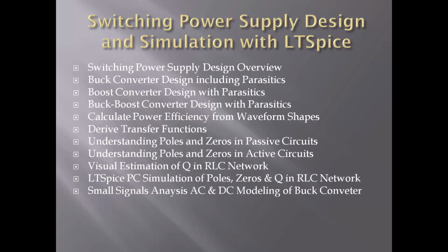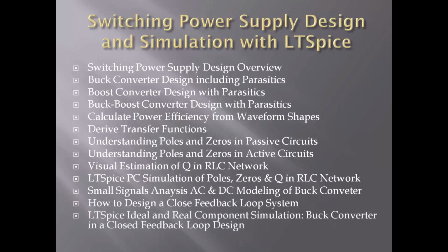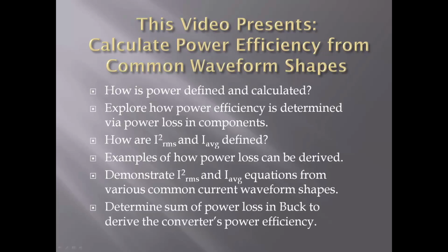Because if we go through a half bridge and a flyback, you have a lot of resistance. You have the resistance of the winding of the secondary, the primary resistors, the bridge RDS ons. We also want to include switching losses, maybe diode losses if we're dealing with synchronous rectifiers. If we do it this way, it's going to be pretty cumbersome. It could be done, and step by step we can do it. But there's a better way.